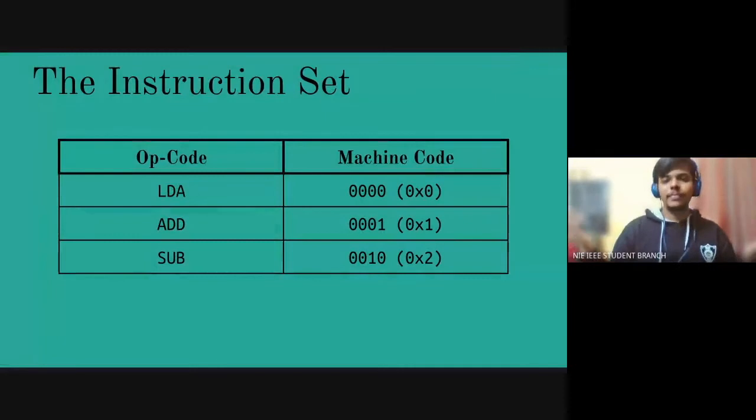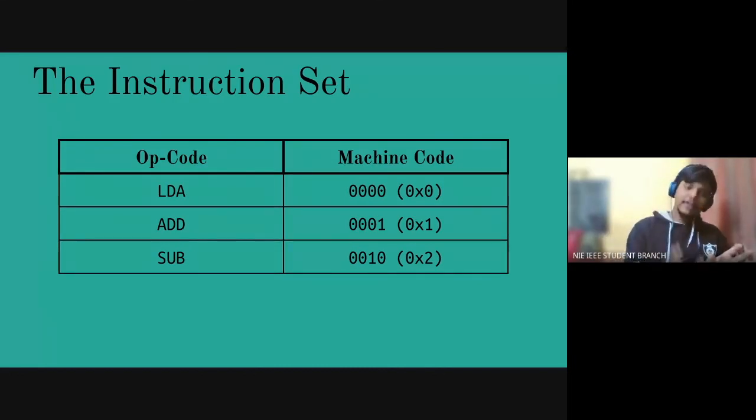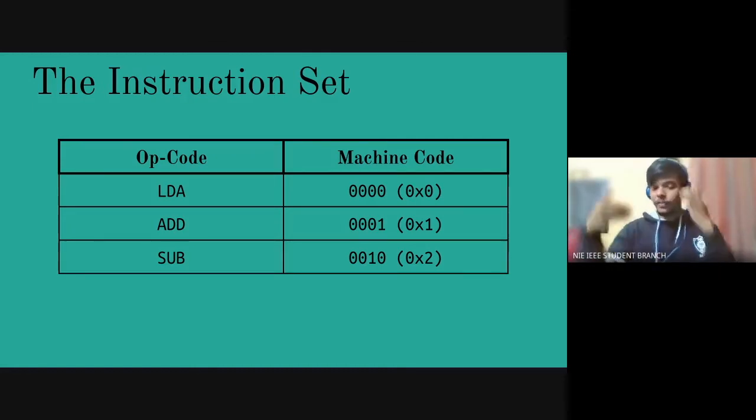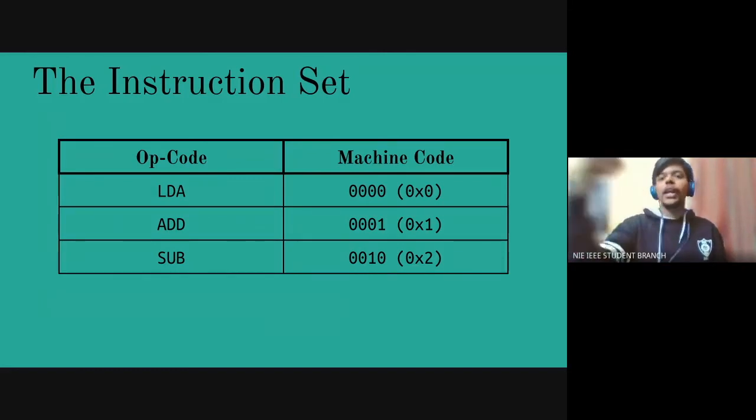So next, obviously like the complement, is subtraction. It is identical to the addition instruction except that you perform subtraction and you store the difference in the accumulator. Everything is the same. Whatever address you give it, it goes to that address, takes the data, puts it into the B register, and then the operation performed is A minus B. If A is the accumulator and B is the B register, you do A minus B and then put it back into the accumulator. Okay, so that's the subtract instruction.